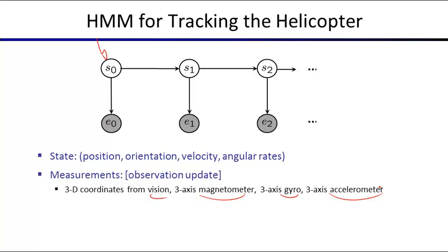The gyro, in the frame of the gyro, will say along each of my 3 axes how fast am I rotating. And then the accelerometer will say along each of my 3 axes how different my acceleration is from free falling. So if you free fall, you measure nothing on an accelerometer. But if you're not free falling, you measure whatever acceleration you're experiencing that's different from free falling. So for example, if you hold up something with an accelerometer, it's not free falling by the amount of acceleration you're giving it against gravity. And so you're essentially measuring gravity, which direction gravity is pointing when you hold your accelerometer.